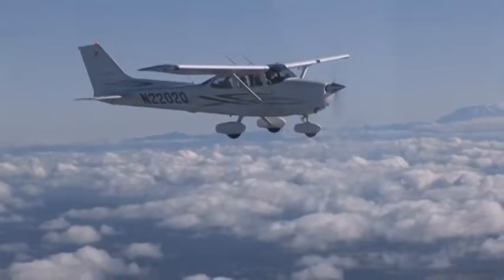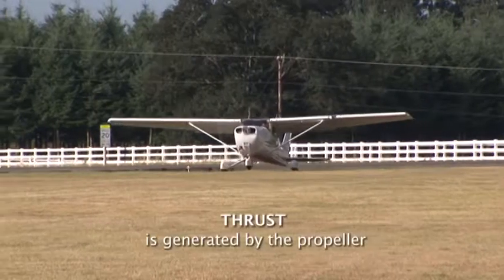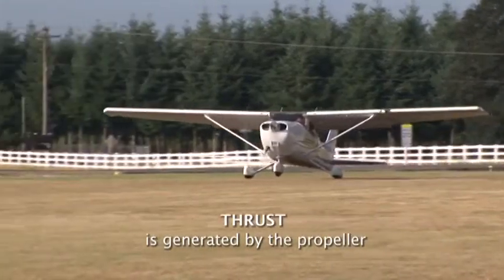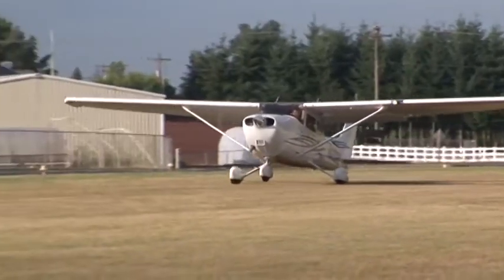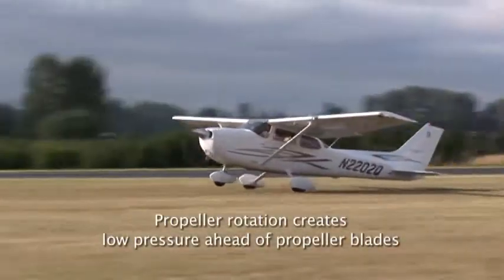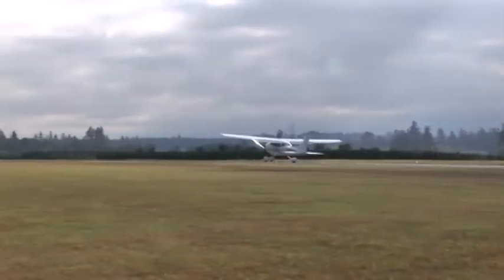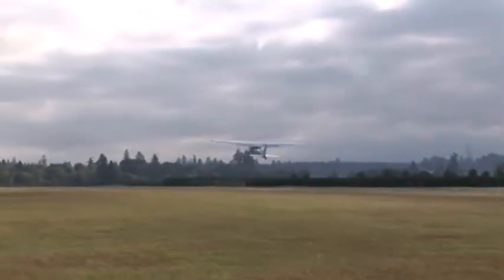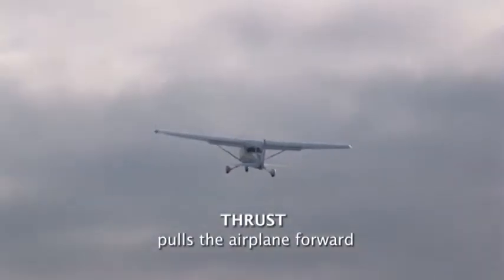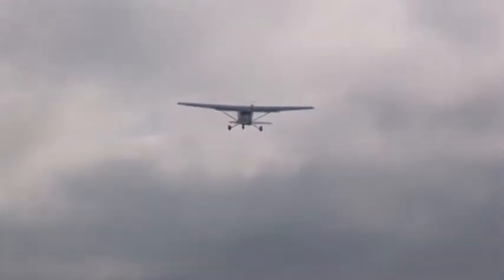The third of the four forces is called thrust. Thrust is generated by the propeller. The propeller blades are curved airfoils. Now, as these airfoils rotate, a pressure differential is created between the front and back surfaces of the propeller blades. This pressure differential manifests itself as a low pressure on the front propeller blade surface and a high pressure at the back of the propeller blade. This result is thrust, and that pulls the airplane forward.